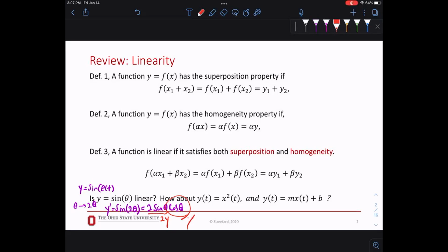So this is not LTI because it's not linear, right? Once you can find one condition that doesn't hold, you just stop, it's not LTI. So now, of the two properties, linear and time invariant, this one is just not linear, right? So it's a nonlinear system. It could be time variant or time invariant. Here it is actually time invariant, it doesn't change with time.